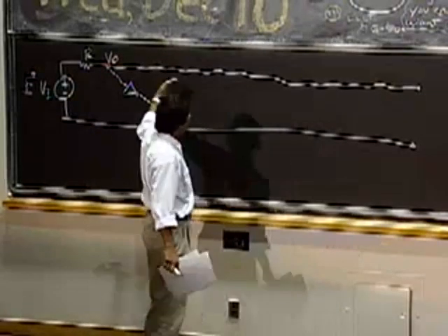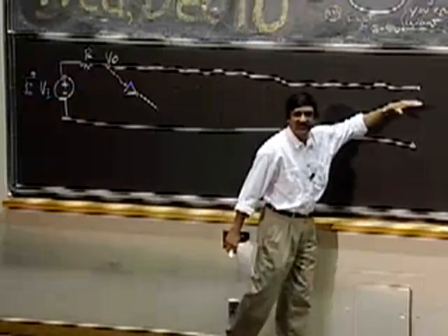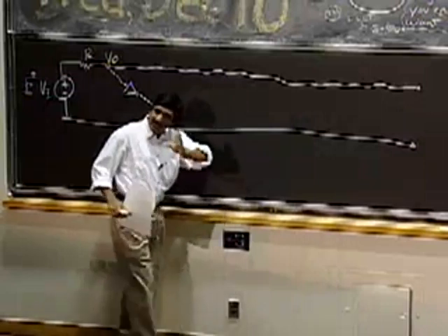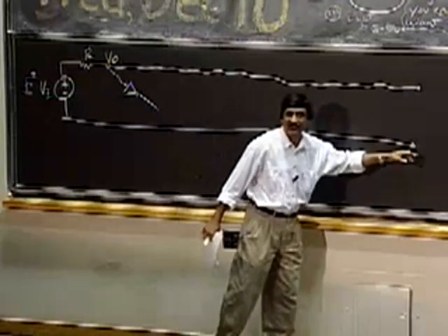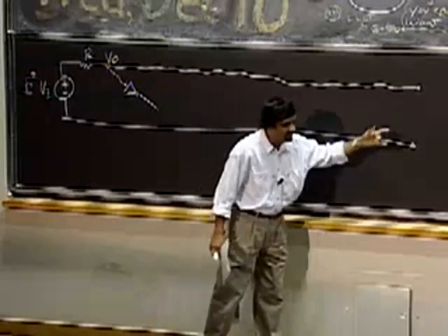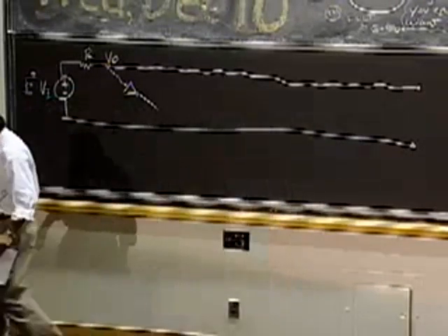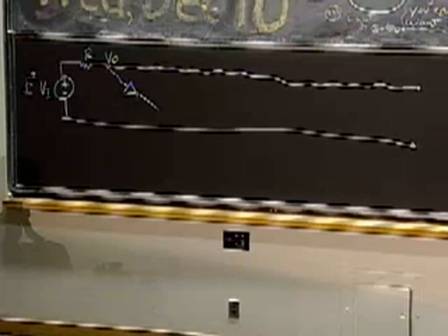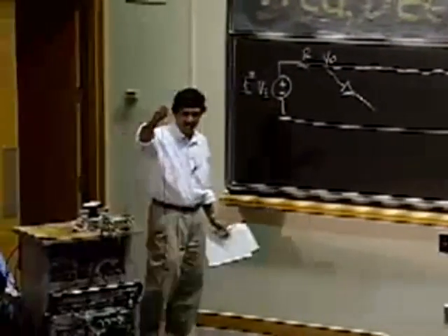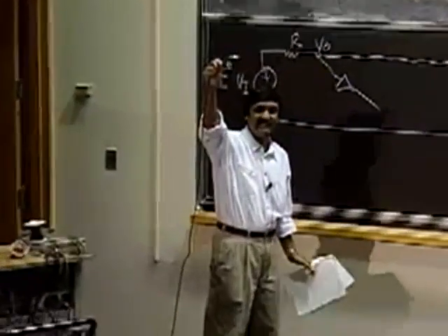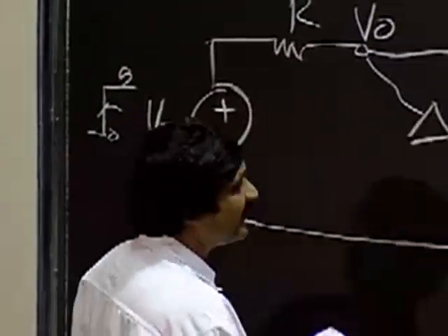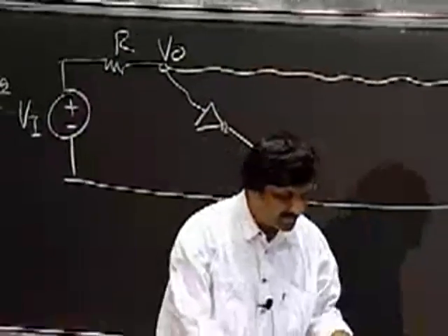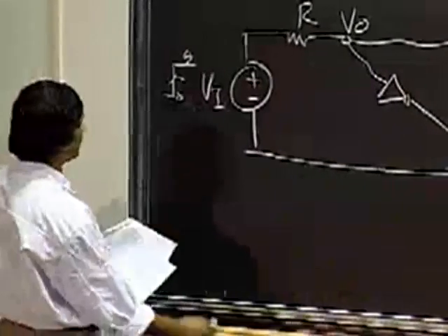It's got a core that carries a signal, and around the core is shielding that is the ground. So that goes a long way, and at the end, it is open. It's an open circuit at the end. I haven't connected anything out there. Open circuit. So something's happening here that's making the circuit behave like this.